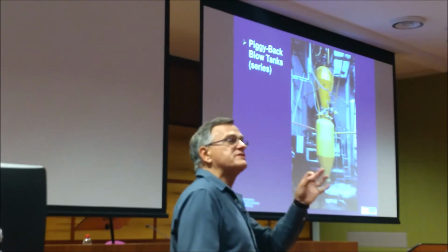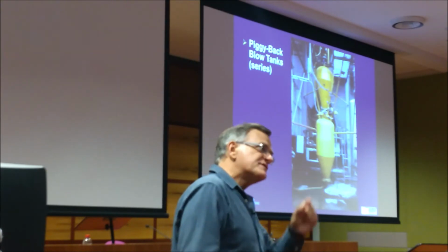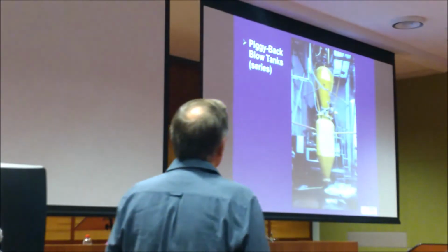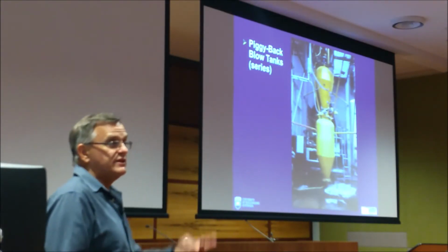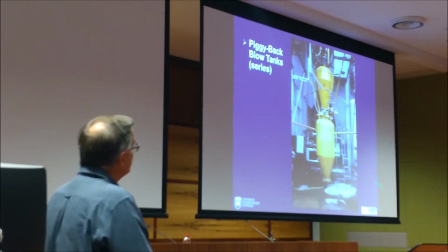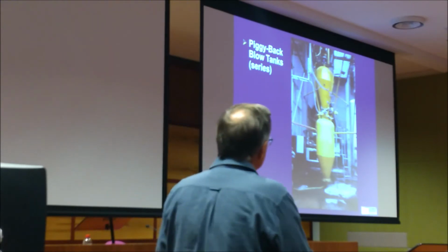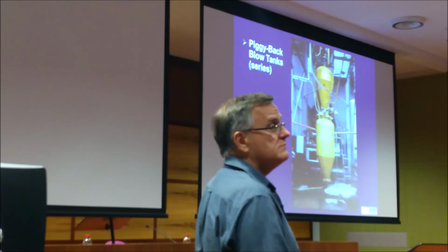And it has to be 100% supply. The tandem system is no good. Just that gap of a few seconds is enough for the torch to go out, the burner to go out. So here we have a piggyback system, or blow tanks in series. You need 2 tanks again, but this top small one is like an airlock. This is your main feeding vessel. There's your discharge pipes, that's a top discharge system.